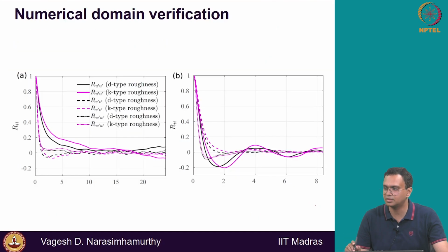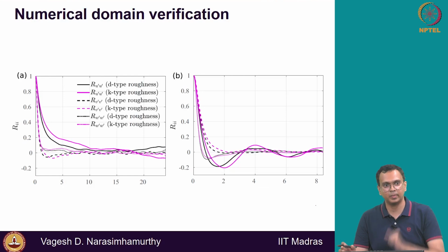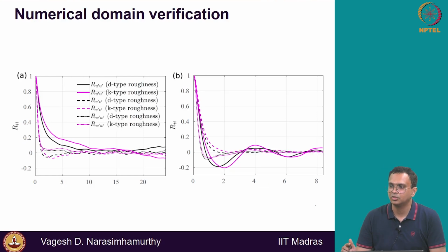Two methods of testing the mesh, whether it's good or bad. Now the domain. The box that you are using in a CFD calculation should be sufficient to capture the large eddies. Generally we may think that, let's say, you have a channel flow, which is shear driven.